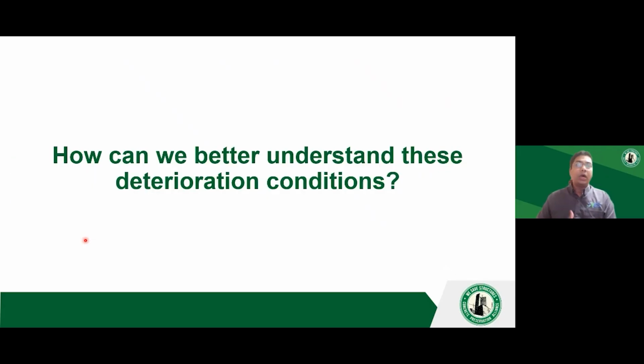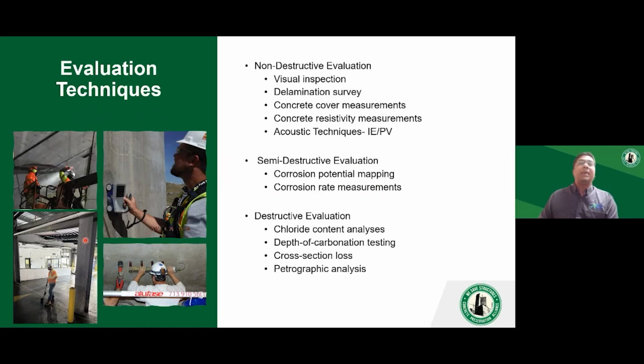Now we know how corrosion happens, what the energetics are for the corrosion. The question is, how do we better understand our structure? How do we assess or evaluate our parking structures? There are many techniques at our disposal. Some of them are non-destructive, where you do not really make an impact on the concrete. Some are semi-destructive, where you would have to drill a hole to make a connection to the rebar or something along those lines. And some of them are destructive, where you need to take a sample from your structure and analyze it for a few properties. I'll talk about these in the subsequent slides.